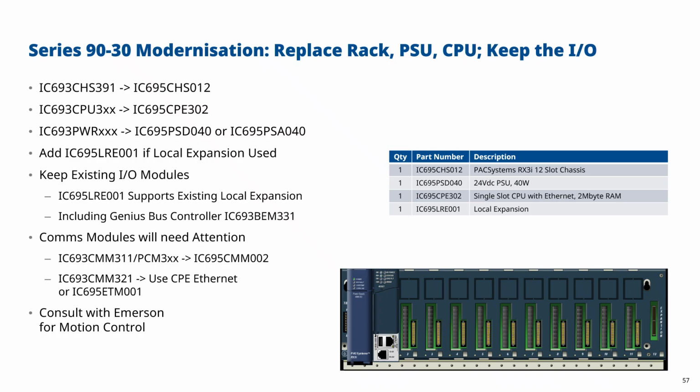And the reason it will still work is if you look at the backplane here, you'll see for each slot we've actually got 2 connectors. There's the bigger connector, which is the new IC695 PCI connector, but we've also got the older Series 9030 IC693, IC694 serial bus connector.